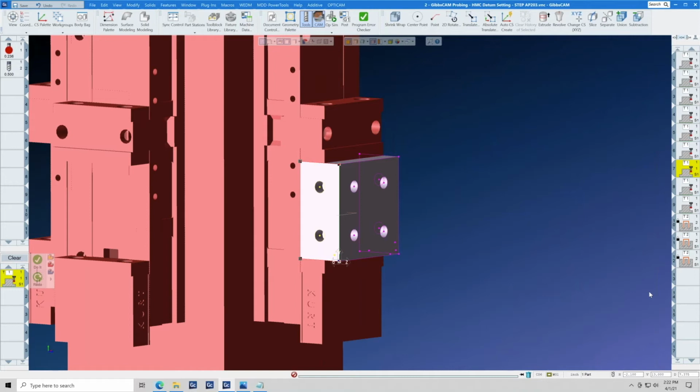Anytime you stop the program to either measure the part or make an offset, you have created variations that can affect the quality of your parts. The solution is add probing cycles and integrate them with your machining operations to create a green button process with consistency and stability. Now, the big one is, what are your expectations?